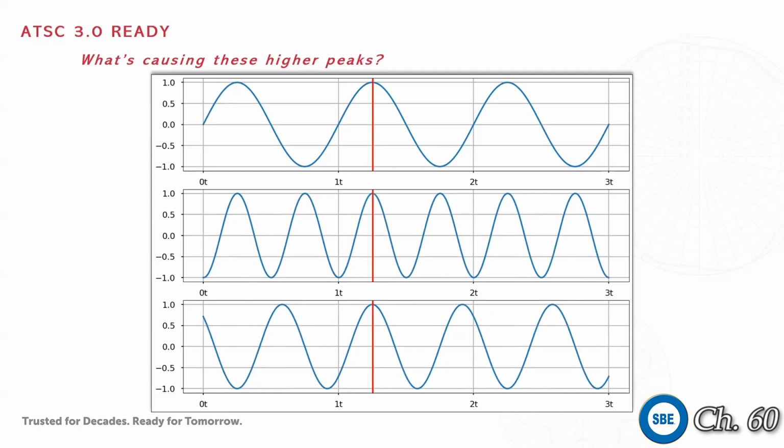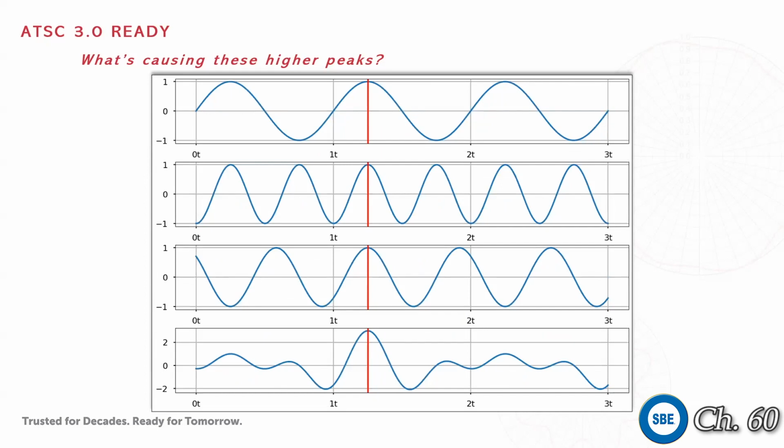That is usually when a number of these subcarriers all align in their phase, which results in a much higher peak in the power. This peak in the power causes a higher voltage. The higher voltage can lead to dielectric breakdown, arcing, and our equipment getting burned, which we want to avoid.